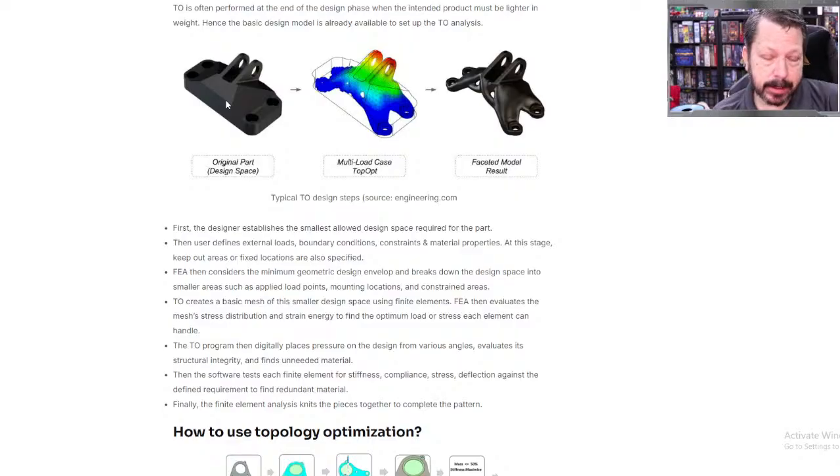There's another process that we'll look at, I don't know if we'll look at this week or next time even, but soon, where it's generative design, where it works backwards. You just give it the constraints. You have to have a hole here, don't put anything there, here are the loads, and it will generate material between those constraints. So that's generative design, and they end up looking very similar, but topology optimization is technically the one we're going to look at today.